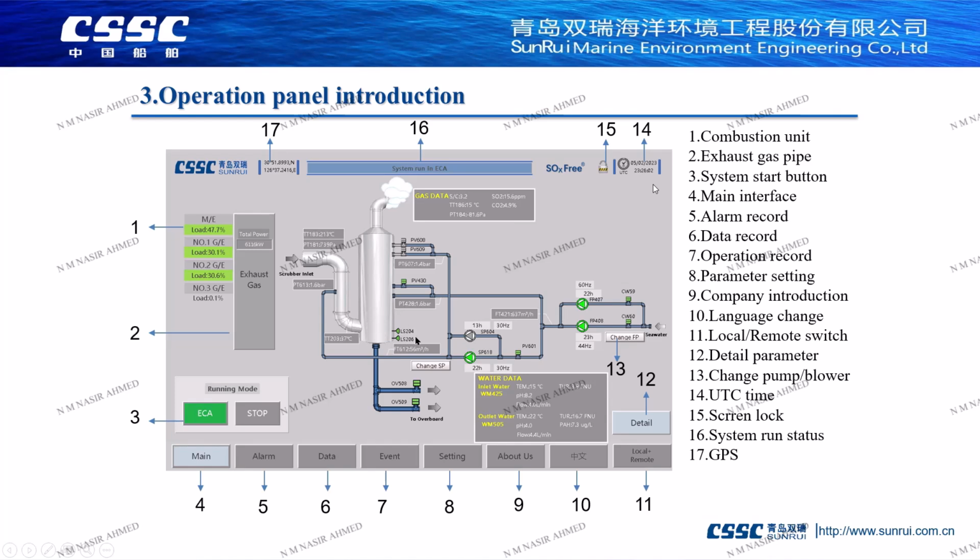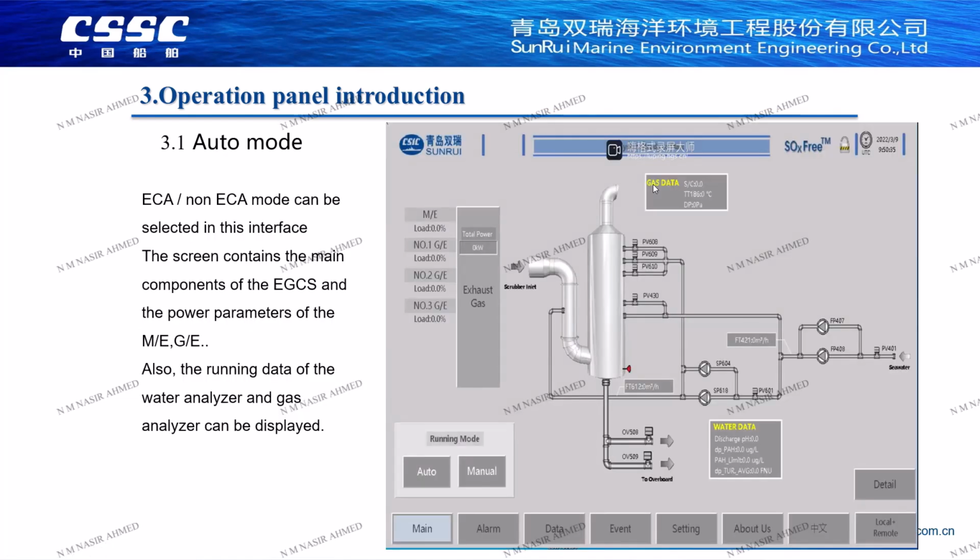And as we can see, at the bottom of the desulfurization tower, we install 2 level switches. The purpose of the level switch is mainly to ensure smooth drainage of seawater. When the water doesn't drain smoothly, the water level will rise, triggering the level switch signal. The liquid level signal will cause the system to shut down, achieving the role of security protection. That is an introduction to the operation of our system.